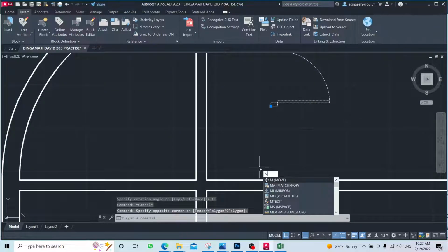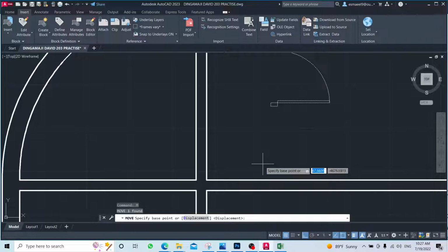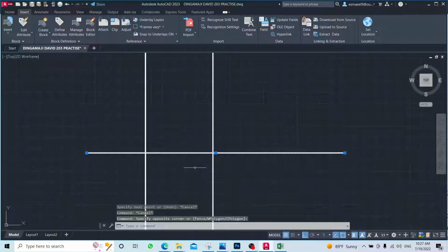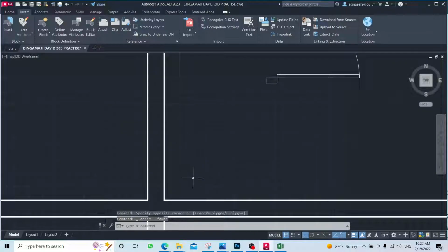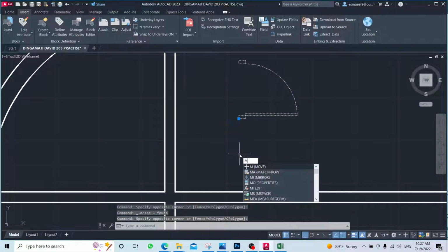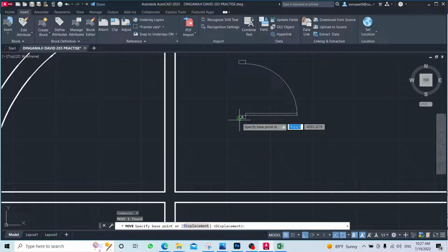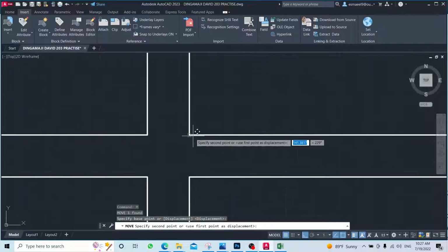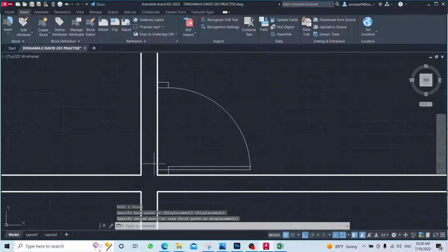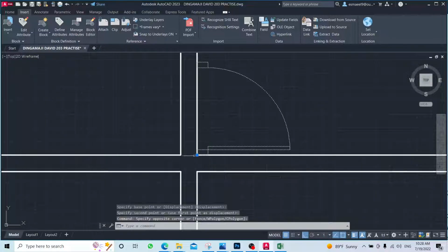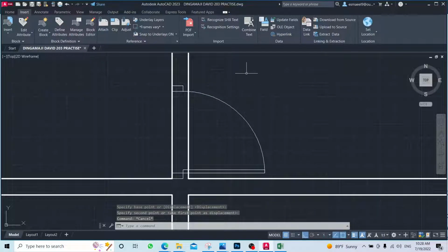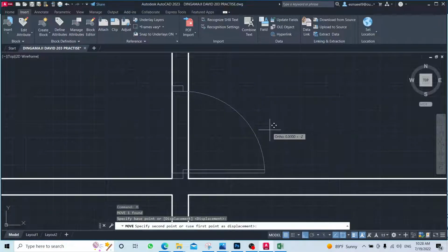Select it, M, enter. Look, this technique while you are creating a door. I want my door to be approximately in here, to start from this point. What I will do, just bring your door, M, enter, for move. Click on this corner, and bring it into this corner. Exactly at the corner. Or put it inside. Start it from here.